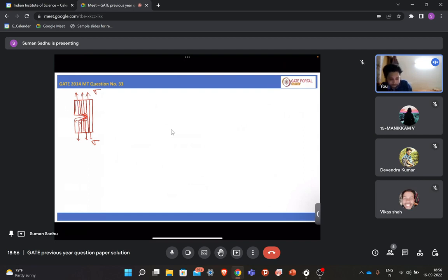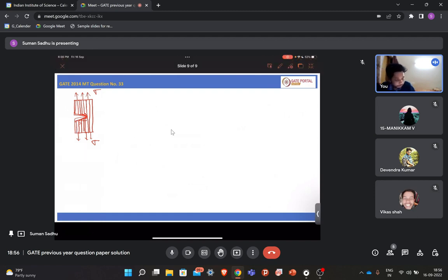So that means in this case, your deformation will be concentrated near the tip itself. Initially your tip was like this. Now when you are loading, too much stress will be concentrated here. Let's say this is the distance from the tip, x. If the stress we are applying is sigma, then at a very far distance from the crack tip, your stress will be sigma, right?